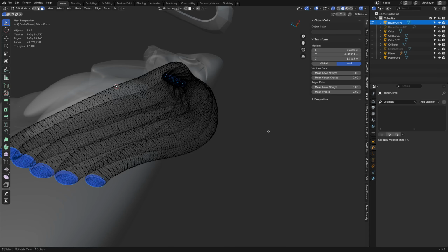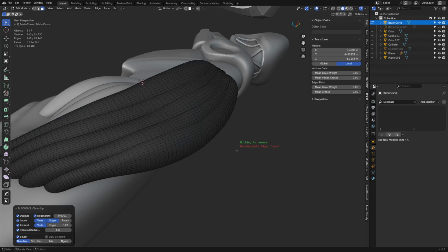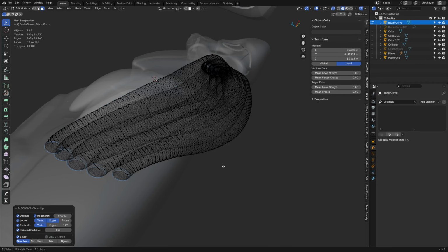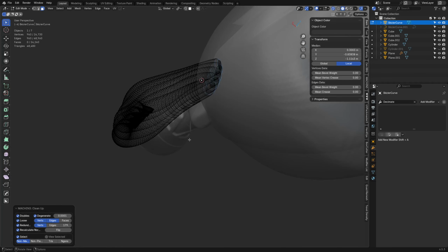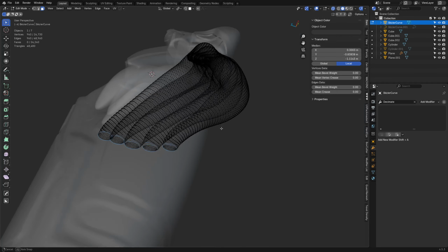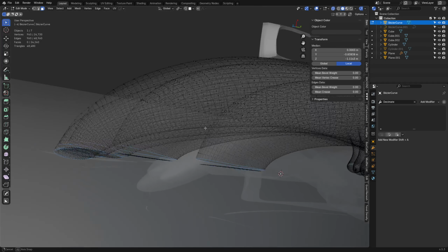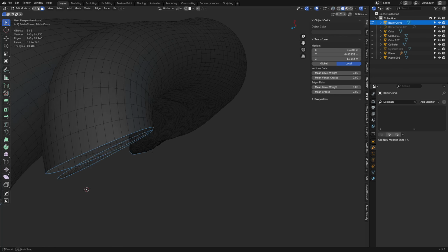So I'm going to press A and F. Oh, with the machine tools feature, let me do this. When you have something like this, you use the machine tools cleanup feature. You see it says open edges or something not found, whatever it says. It's a little red mark there, right? Non-manifold edges found. Okay, and it highlights all of them in X-ray. So those are all your open edges. I know that's the end cap, so I just press F. It fills them. I thought I filled these with the original curves and then I converted it to the mesh, but it's a little bit odd. I guess they separated or something. Yeah, it's like it separated them somehow.